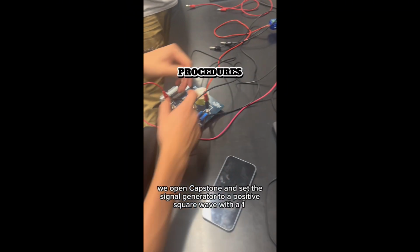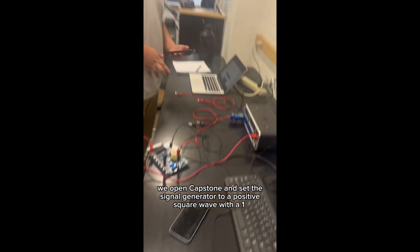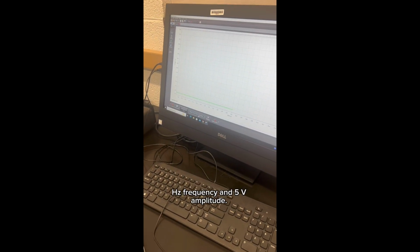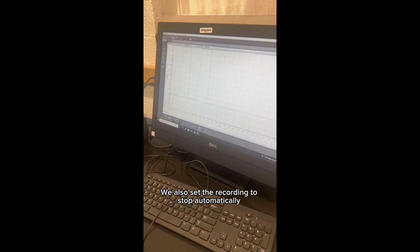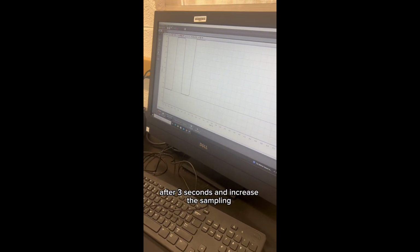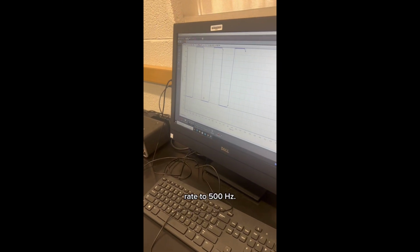First, we open Capstone and set the signal generator to a positive square wave with a 1 Hz frequency and 5 V amplitude. We also set the recording to stop automatically after 3 seconds and increase the sampling rate to 500 Hz.